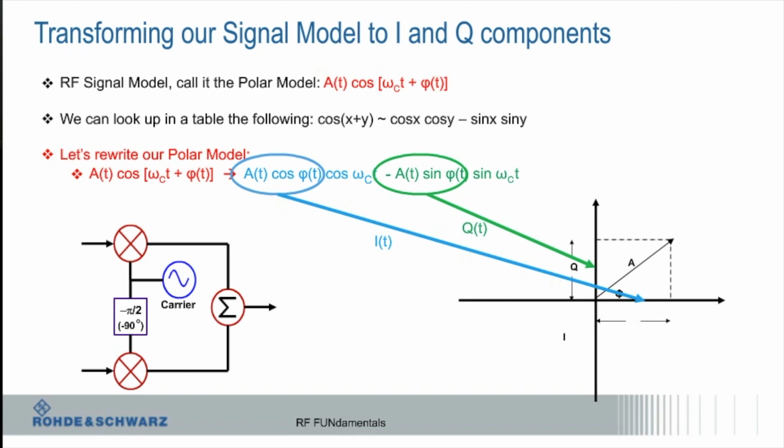It's actually a really simple, inexpensive circuit to make. That's why they use it for everything. Basically, you have two mixers and then a phase delay between them. So when these combine, they come out with a phase difference of 90 degrees between the two, and then they get combined.